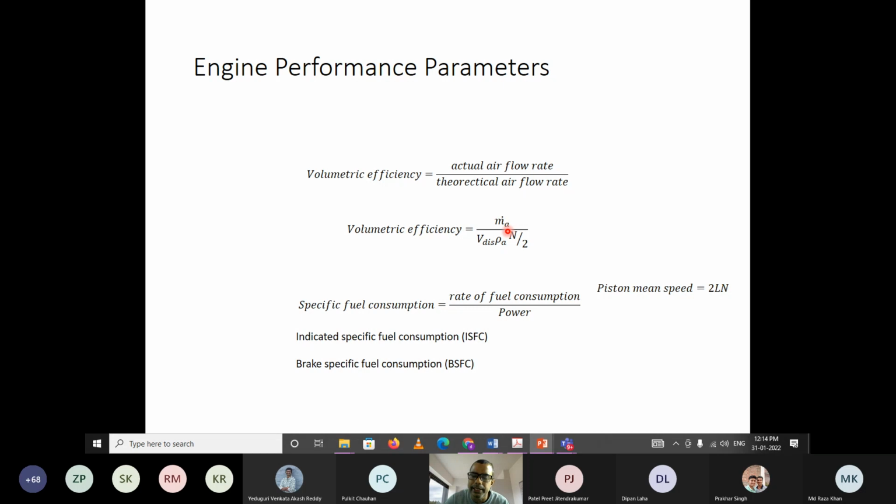In fact, there is a lookup table already stored in the ECU, and depending upon the engine input parameters, the ECU will trace, according to engine speed, throttle opening and manifold pressure, whatever the way it has been stored, what the mass flow rate of the air is.